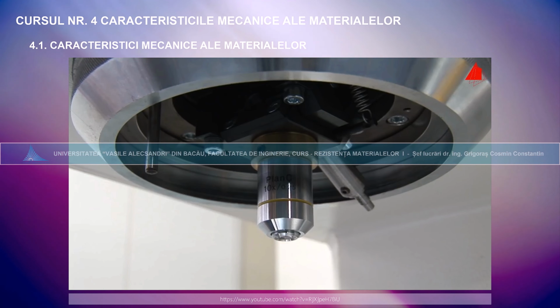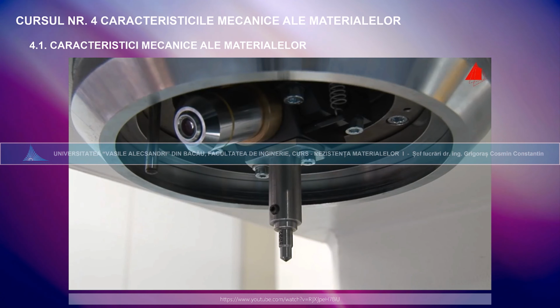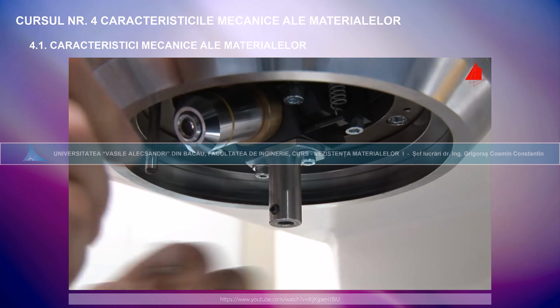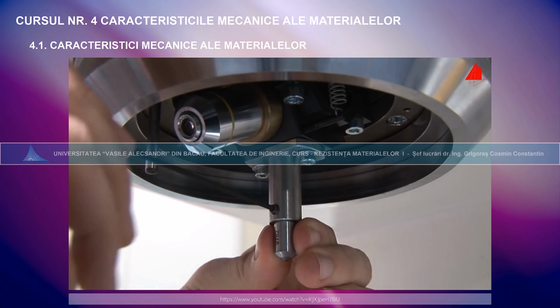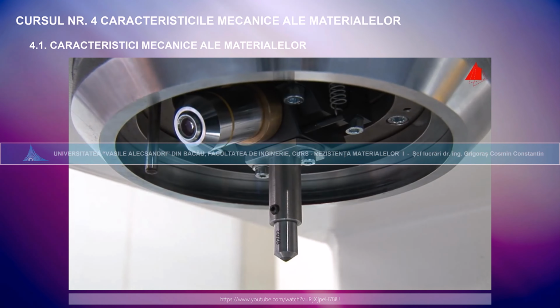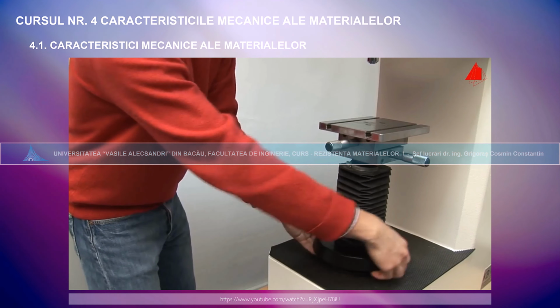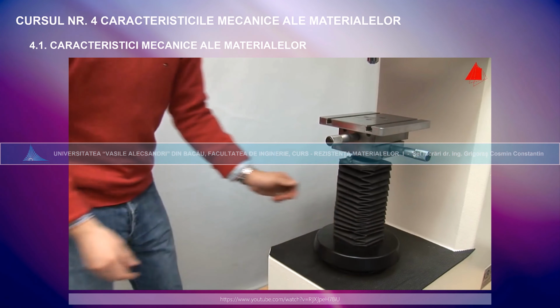Below the control panel, a microscope lens with a digital camera and an indenter are installed. These two elements are connected to each other and rotate towards the test piece as required. It is also possible to select and exchange the indenter, so different methods of hardness testing can be conducted on the same testing machine. The support table can be adjusted in height, so the test piece can be positioned at the correct distance to the microscope lens and the indenter.